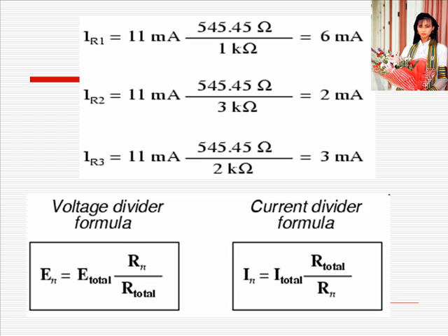It is quite easy to confuse these two equations, getting the resistance ratios backwards. One way to help remember the proper form is to keep in mind that both ratios in the voltage and current divider equations must equal less than 1. After all, these are divider equations, not multiplier equations. If the fraction is upside down, it will provide a ratio greater than 1, which is incorrect.